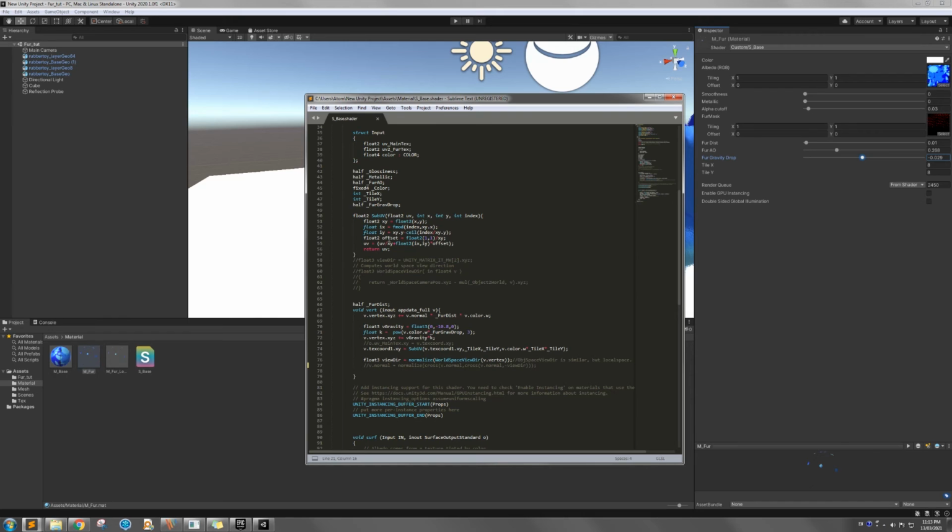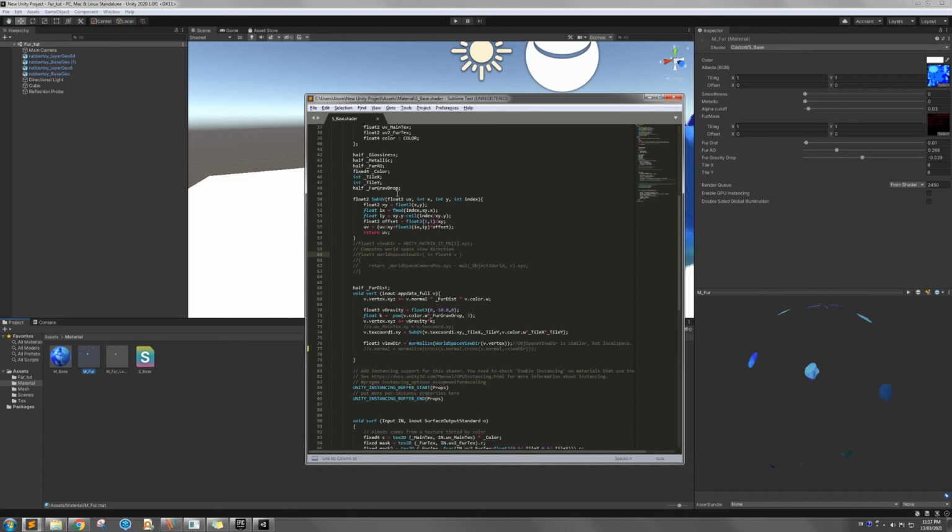Also, I create the function to sample the UV. It's a similar function to what I did inside Unreal. In the sub UV function, you need to input the current UV coordinate you want to use, and you need to put in the maximum sections on the X and on the Y. In this case, 8x8, and also which index you want to access.